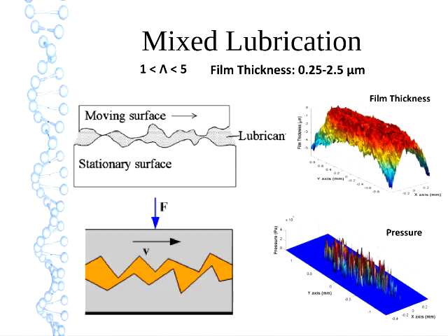And you see a general dome-like shape, but there are a lot of spikes. And those spikes are the areas where you have asperity contacts, and the actual lubricated areas are not supporting nearly as much of the load.